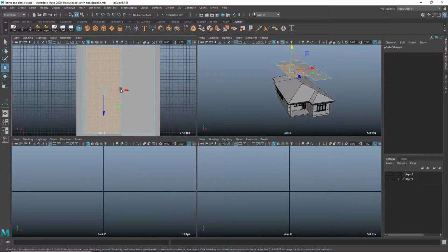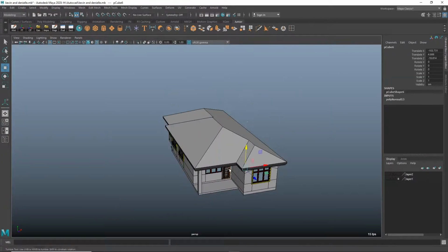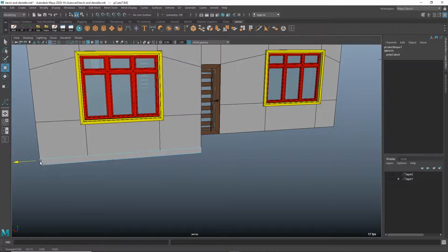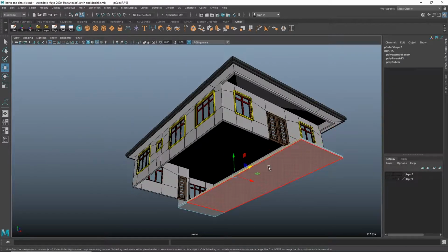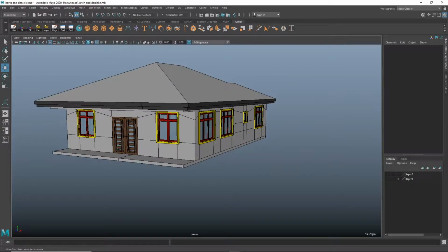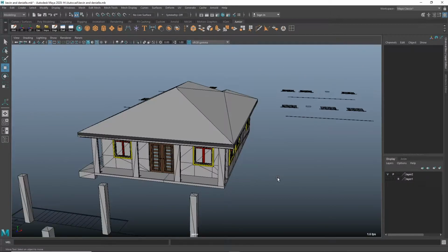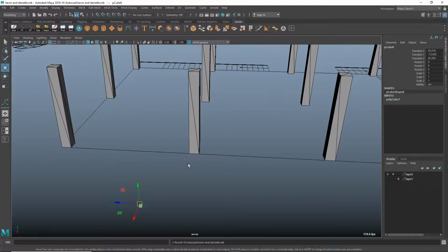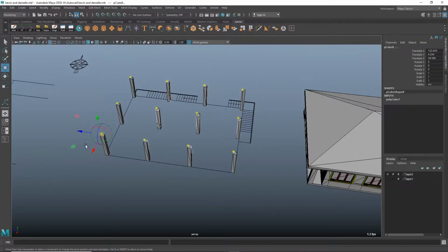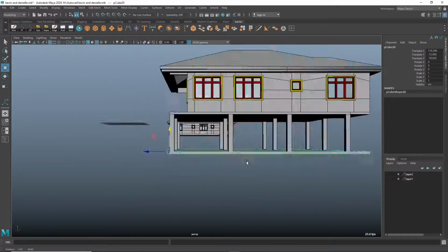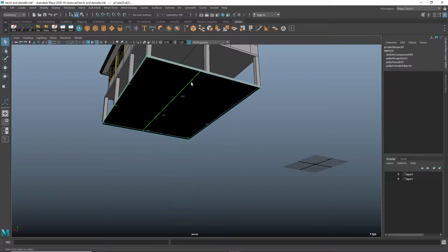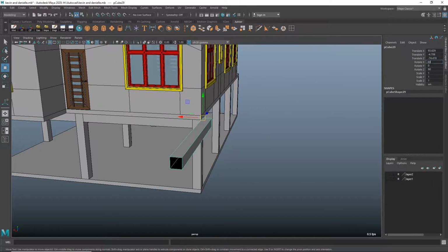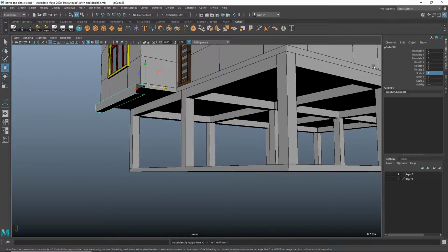So here I'm just doing the ceiling for the inside, because going back to the same thing with the normals being black versus gray, you can see if a mesh doesn't have the normals in the correct direction, when you look at it from the dark side, you would actually see straight through it. So if you do a render of the house from the ground floor looking up through the window, and the normals for the roof are flipped, you would actually see the sky inside the house. So you need to put in the ceiling and then flip the normals for the ceiling. So you would have the gray on the inside of the room, and then the black would be between the roof and the ceiling itself.